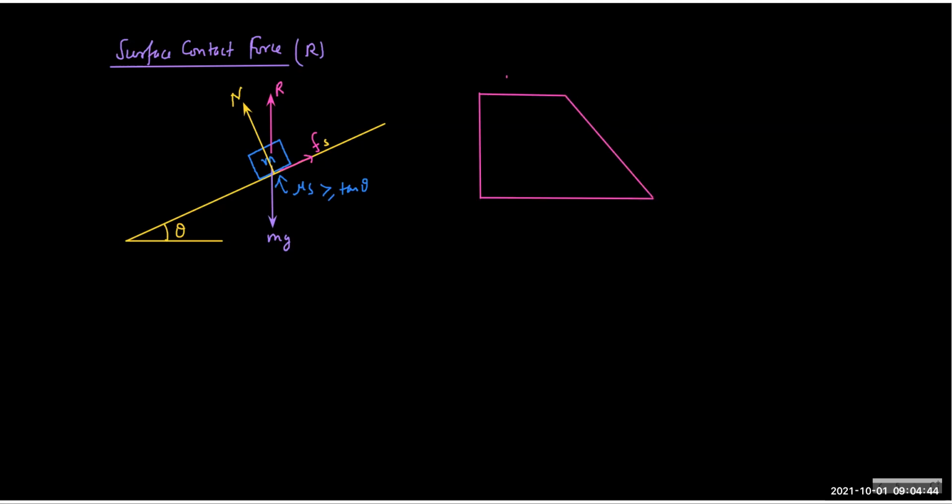So when something remains at rest is a very interesting case. If the friction is sufficient to hold the block at rest, it means it will be like glued to the object. So it will behave as one single object. So the reaction force, as we discussed, acting on the block is upward and the gravity is downward. Now I'm not drawing the normal and friction separately. I'm drawing the reaction force of the surface as a whole. So now let's try to draw the FBD of the wedge separately.